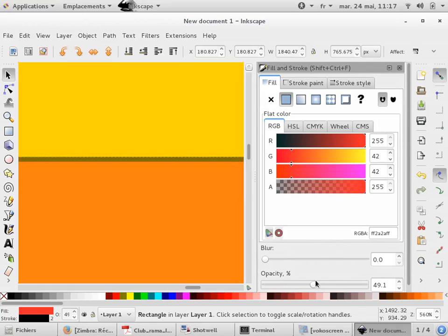You should mention that the PDF handles transparency. Yes, I put it explicitly. When you want to deal with transparency in your vector graphics, Inkscape, at least on my PC, cannot handle the transparent PDF properly. Maybe Inkscape cannot produce a nice PDF which handles transparency, but I produced it without Inkscape, from Matplotlib. So if you deal with the PDF format, maybe it's better not to use transparent or blurred images.